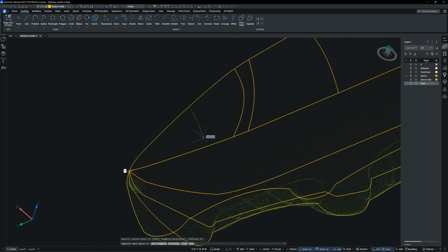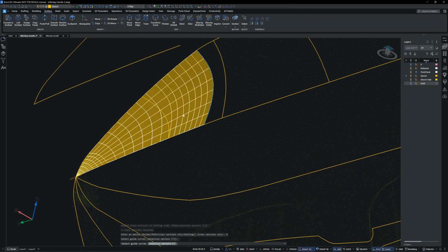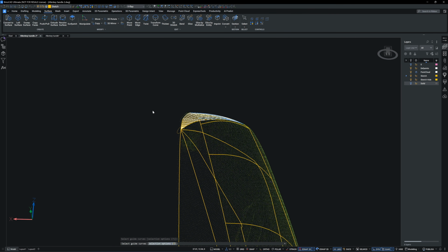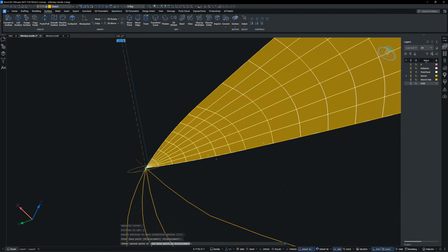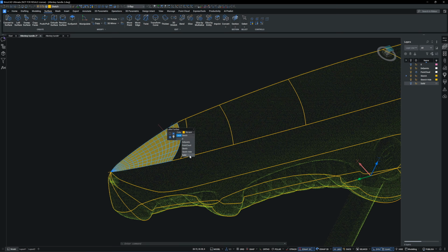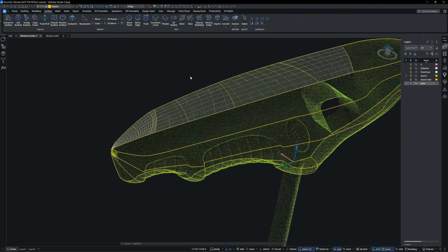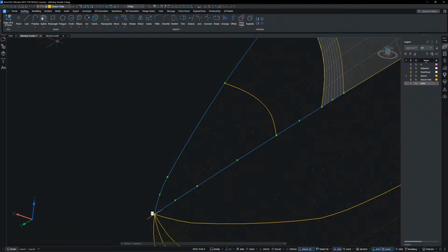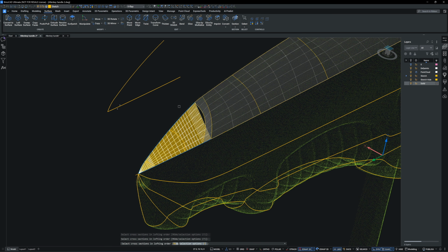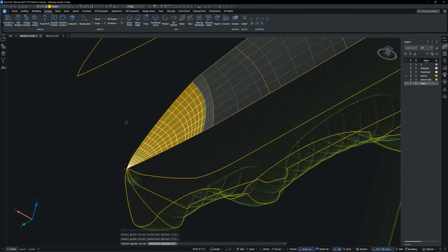When the surface boundary is too long, the loft command won't run. You will need to experiment a bit to learn where to break the boundary lines and where to place the guide rails. When the loft command successfully forces the guide rails, they will turn blue when selected. If they don't, it means you need to add more rails to break the boundary into smaller segments. Here I'm adding one more guide rail to force a smoother curve. You may need to switch the render mode to check the tangency of the surface.